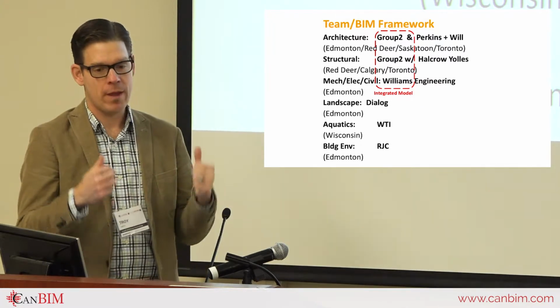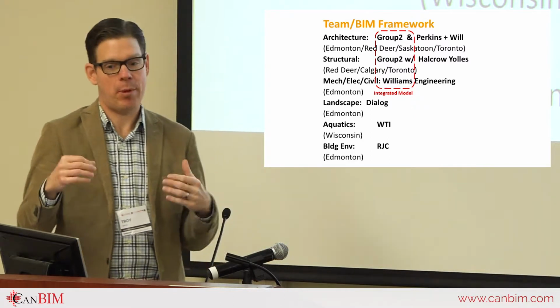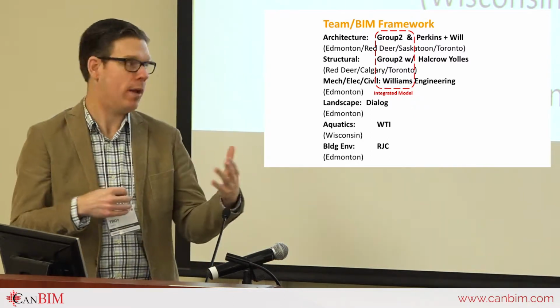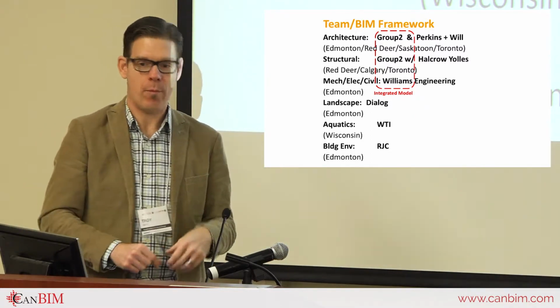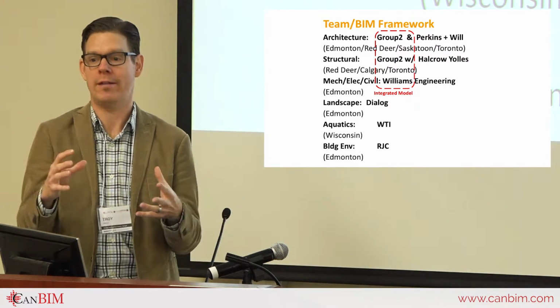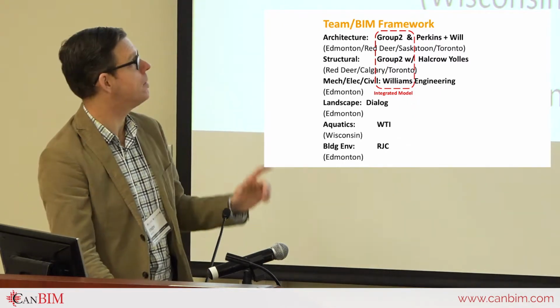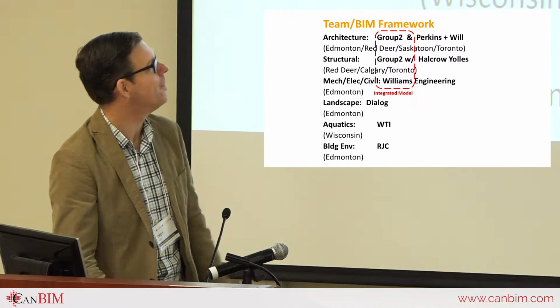Because as a firm, we had to get a whole bunch of extra hardware that we had to buy to actually be able to make that even happen. So that when Williams Engineering decided to sync their model at 3 o'clock, it didn't crash the whole model so that architectural and structural was locked out at that point. So that was a massive lesson learned for us. So we typically don't do integrated models anymore.